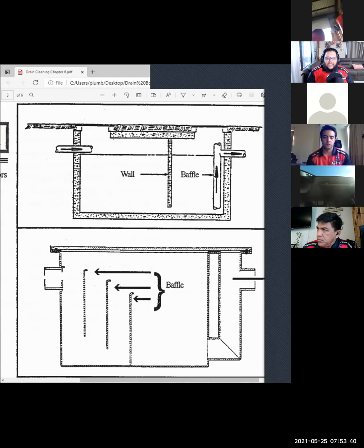If you pull that manhole and that water's full to the rim, next step is to go pull the sample box manhole, check if that's full. If that's not full, then now you're dealing with a full grease trap. If the sample box is full, you're dealing with a mainline stoppage past the grease trap.